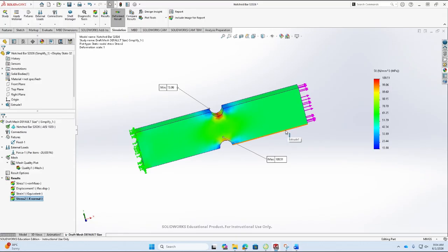Anywhere, either here, right, or here, away from the concentration points. So how can you check this number? Obviously, you are getting this green. Now, if you look into the legend, that can be any number between 80 and 51, isn't it? That green shade that you are seeing here. It's difficult to tell, isn't it? So we need a more accurate way of finding this out. So to do this, we go on to plot tools. In the plot tools, you go on to probe function, okay?